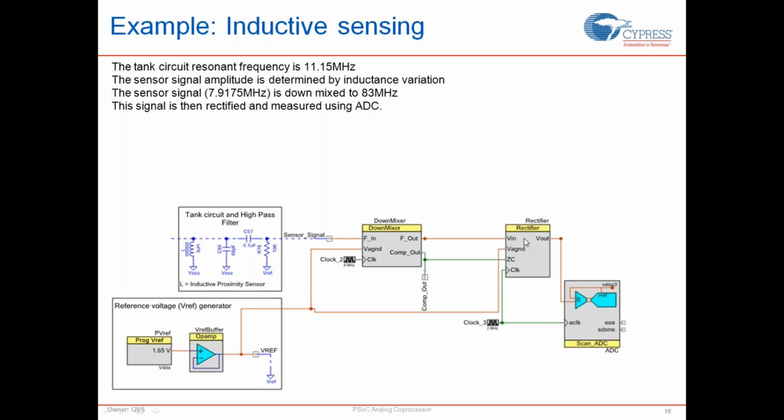So what you're effectively building is something like a synchronous rectifier. You have a digital signal that determines what kind of gain you want. Every time this is high, the rectifier's output is going to gain by 1. And every time it's low, its output is going to gain by -1. So every time this signal is above 0, you're going to gain by 1.